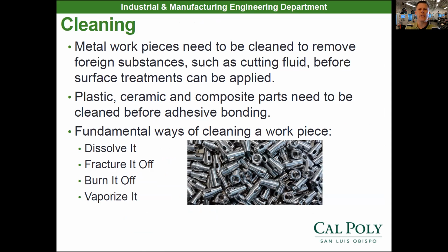They have to be cleaned, and you have to remove any types of oil or foreign substances, such as the cutting fluids, before you can even apply a certain surface treatment. Plastic and ceramic and composite parts need to be cleaned before adhesive bonding. If you've ever tried to adhesive bond something with oil on it, it just comes right apart afterwards. The adhesive doesn't actually work unless you have nice, clean, prepped surfaces.